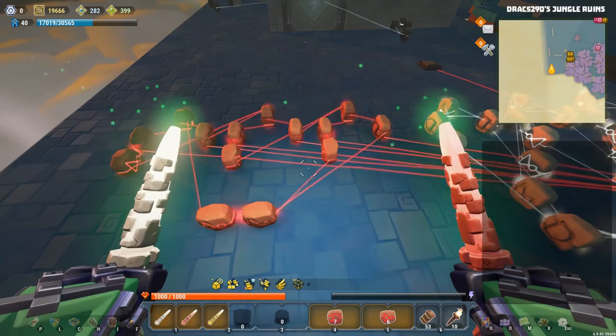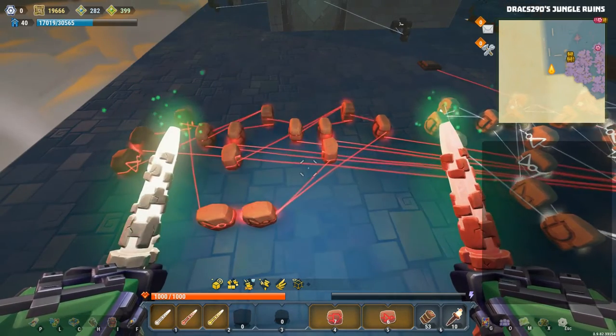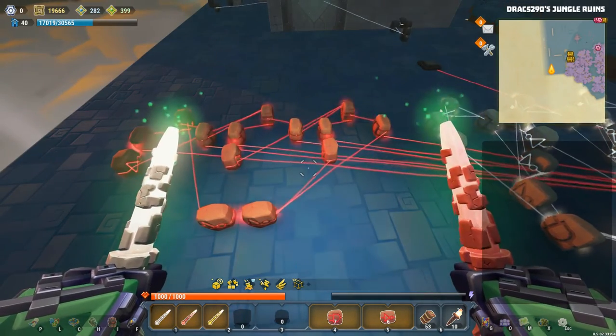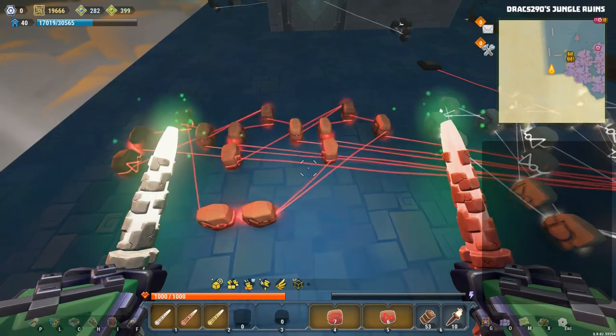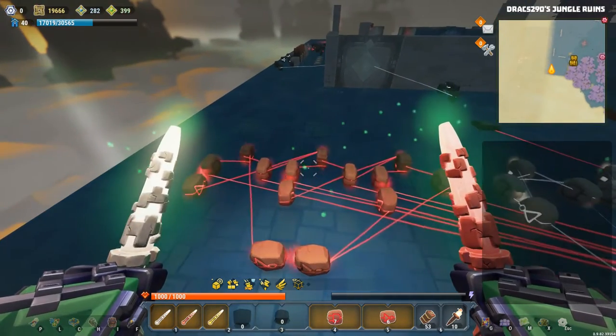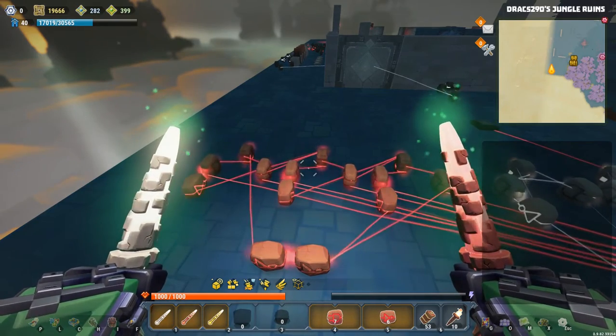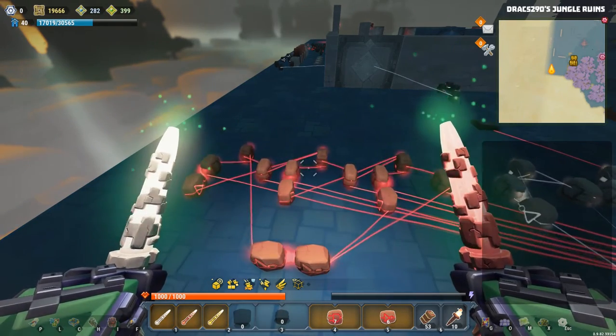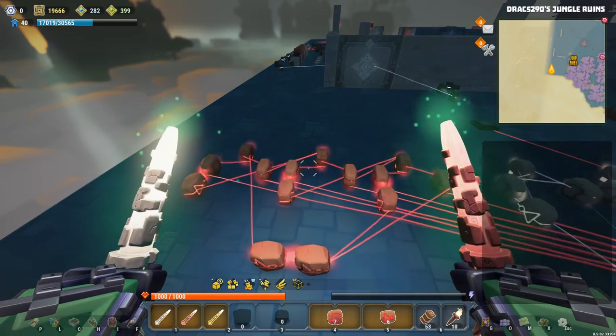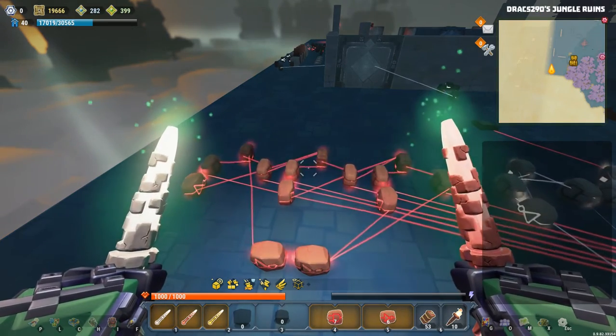So the last little thing we need to do here is a little bit of protection. There's 2 states that we don't want this counter to ever be in. We don't want this counter to ever be all off, and we don't want it to ever be all on, because it's a sequencer, it's not a counter. So if they're all on, nothing can happen, it's just going to stay all on all the time.